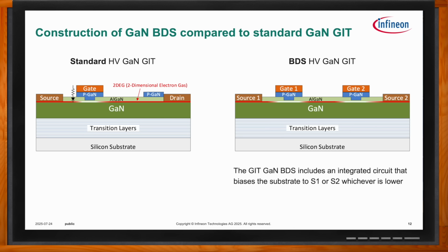So just to make this clear, a typical Schottky gate GaN device has a dynamic RDS on in the range of, say, 25 to 30%, meaning that when you first turn it on, it might not be that 1 ohm device. It may be 1.3, and it has a time constant to approach the 1 ohm.